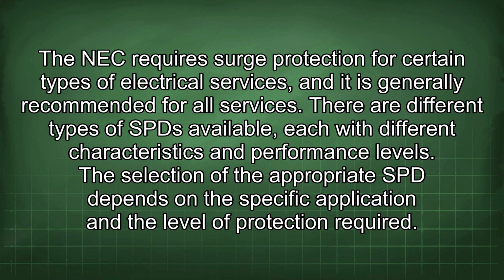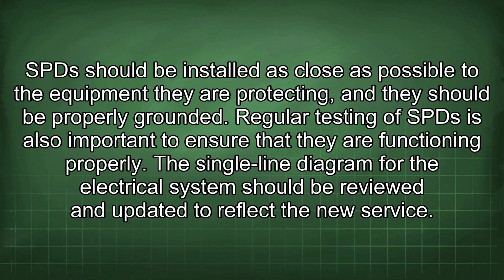The NEC requires surge protection for certain types of electrical services, and it is generally recommended for all services. There are different types of SPDs available, each with different characteristics and performance levels. The selection of the appropriate SPD depends on the specific application and the level of protection required. SPDs should be installed as close as possible to the equipment they are protecting, and they should be properly grounded. Regular testing of SPDs is also important to ensure that they are functioning properly.